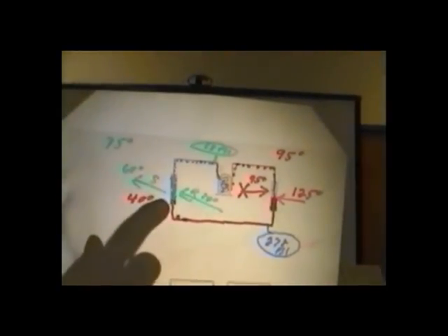And if we look at a PT chart, let's go back and use it. So if I look at the PT chart and I come down on my pressure, 68 psi is about 40 degrees. So I hope you understand that all we need to do is put our pressure gauge on there to know the temperature of the evaporator. Is this clear?